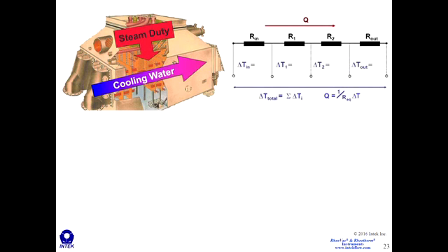Now the heat transferred from, call this point A, to point B over here, through thermally resistive layers, these R's here, is directly proportional to the temperature difference between point A and point B by 1 over R. So we've given that equation here, Q equals 1 over R equivalent times delta T, the temperature difference from point A to point B. And so this R equivalent is just the summation of these impedances.